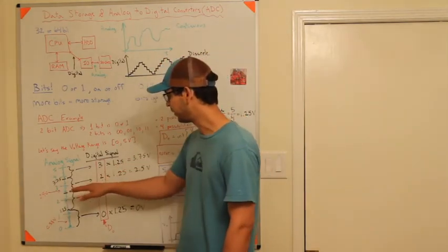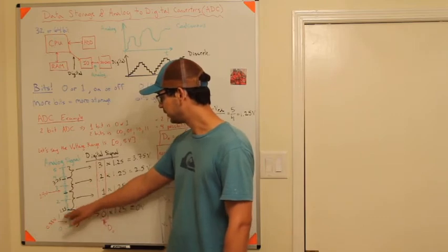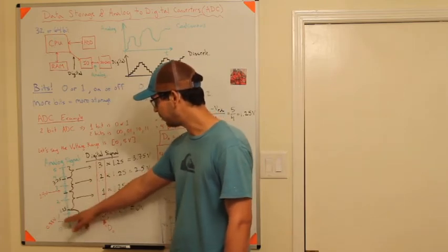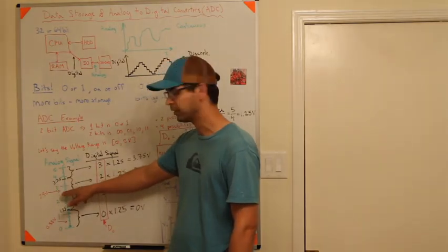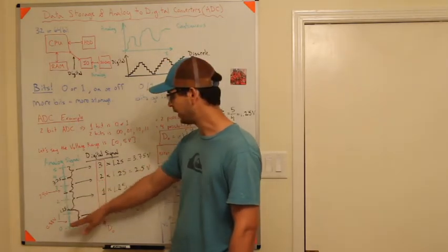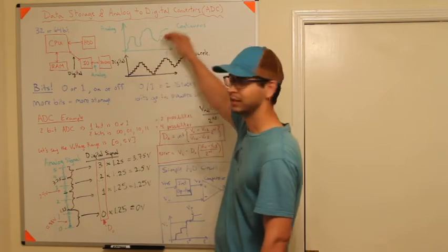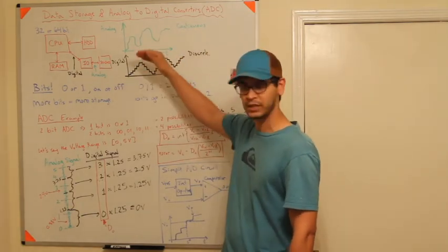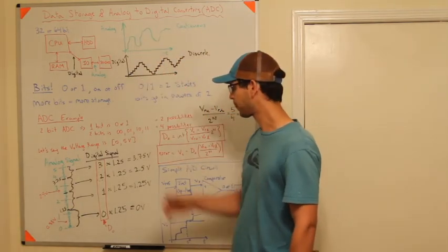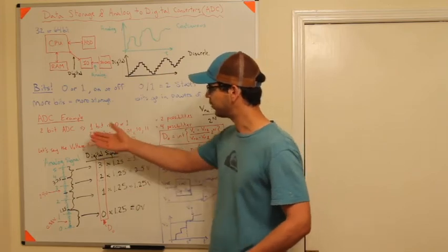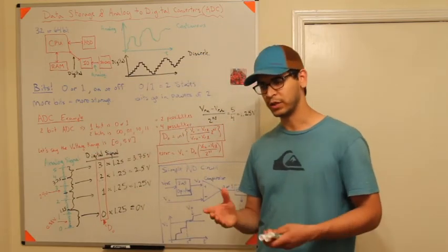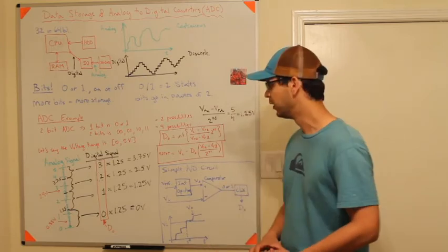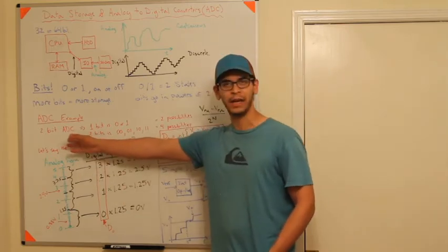So that's less, but still, depending on what my input voltage is, in relation to the closeness of the next discretization on this ladder, I could potentially have a ton of error. And the reason why is because I only have 2 bits. So if you're programming an Arduino, or you're designing an Arduino or a Circuit Playground, are you going to put a 2-bit ADC on there?